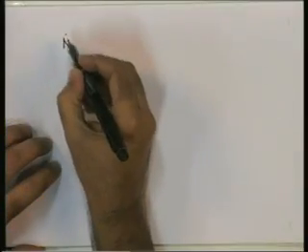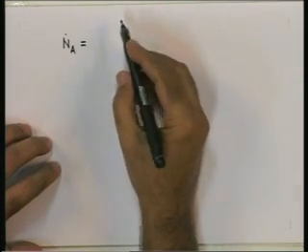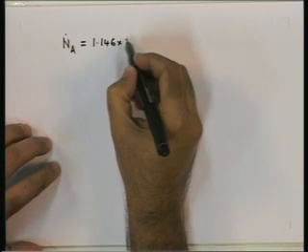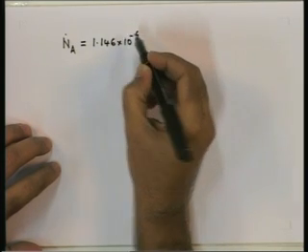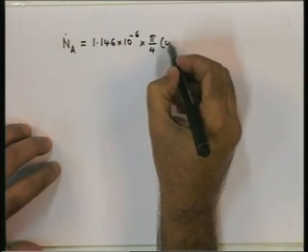We want to determine the leak rate in terms of kilogram per second of ammonia. So, first we calculate the molar flow diffusion rate of ammonia, which will be the molar flux multiplied by area, which will be pi by 4 into d squared.